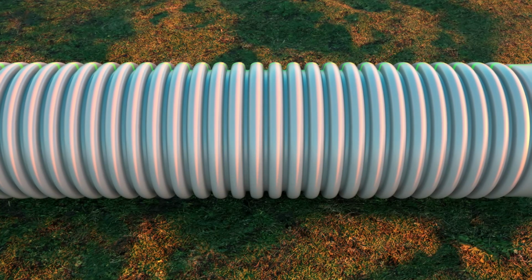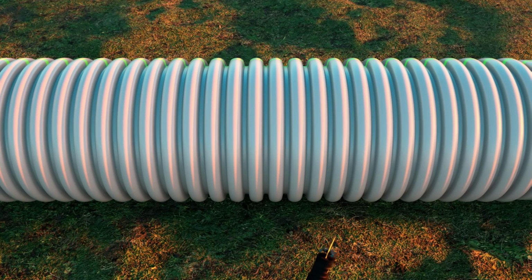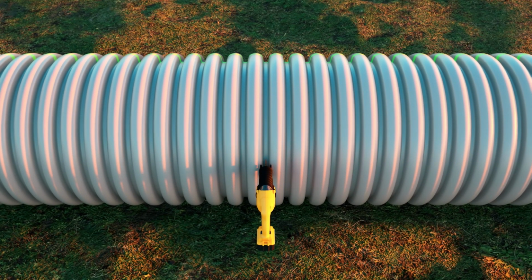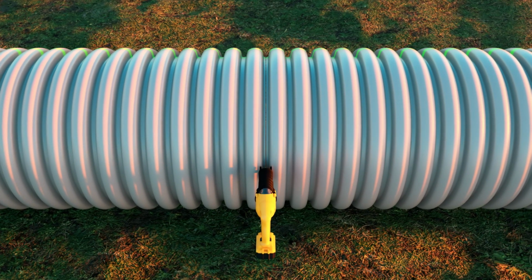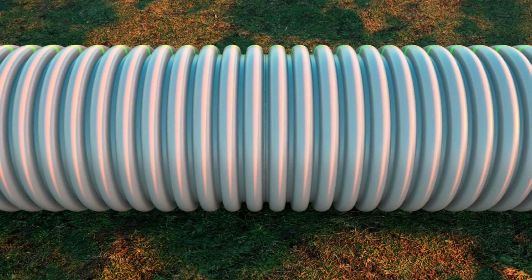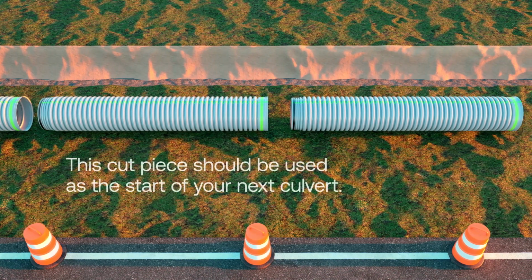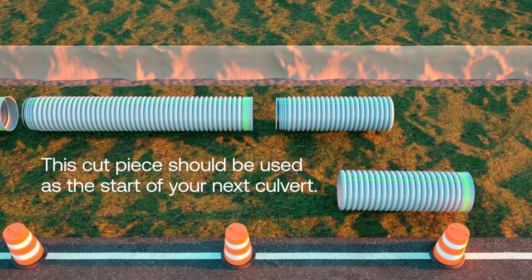If the pipe needs to be cut to the appropriate length for your project, use a reciprocating saw with a coarse blade. Cut the pipe in the valley of the corrugation to the appropriate length. Roll the pipe away as you cut with the saw. Deburr the end if needed. Do not discard the extra piece of pipe that was cut off. Simply place it to the side so it will be ready to be staged for the next culvert.